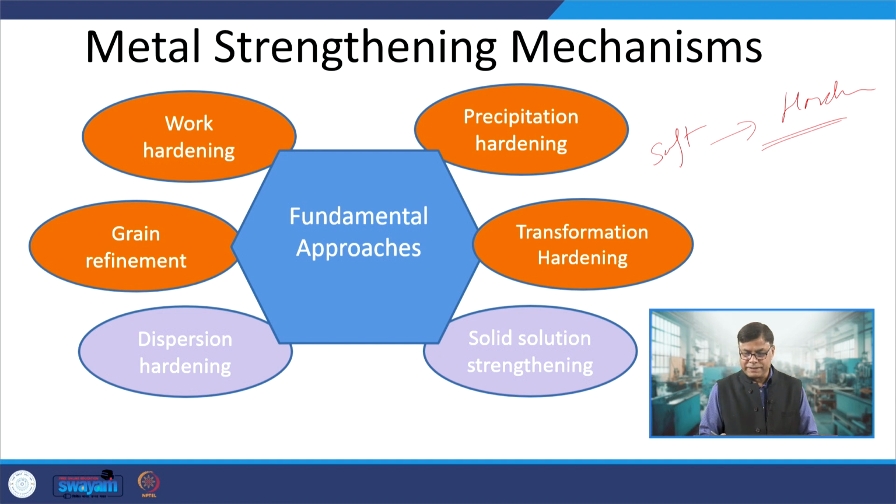Okay. So, what we try to do is, at room temperature, if the plastic deformation is causing the formation of soft to hard phases, then this will certainly compromise the ease of deformation. But if such deformation is carried out at high temperature, it may not lead to the formation of the hard phases from the soft phases due to the deformation. Okay. So, there is another important thing, the temperature at which deformation is carried out is extremely important.